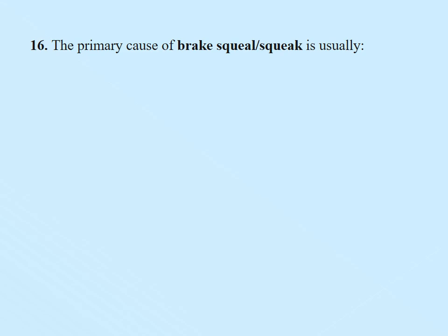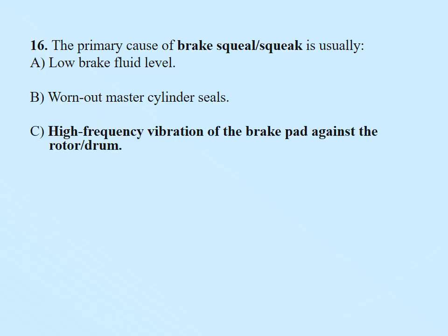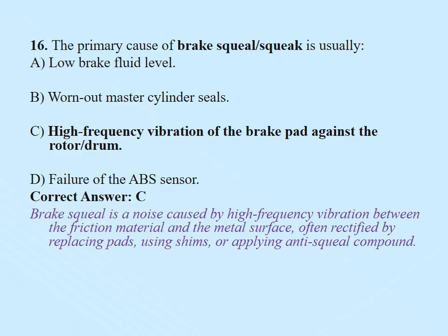Question 16. The primary cause of brake squeal or squeak is usually: A, low brake fluid levels; B, worn out master cylinder seals; C, high frequency vibration of the brake pad against the rotor or drum; D, failure of the ABS sensors. Correct answer is C, high frequency vibration of the brake pad against the rotor or drum. Brake squeal is a noise caused by high frequency vibration between the friction material and the metal surface, often rectified by replacing pads using shims or applying anti-squeal compound.